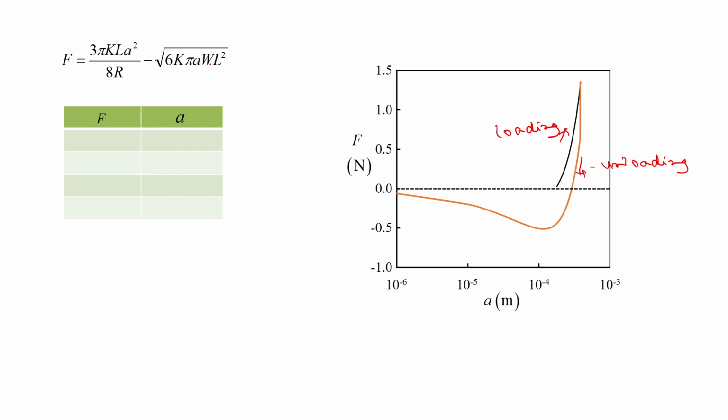So, this is the work of adhesion, right. During the loading part, let us say we start from some finite value of the contact area, at which time the load is estimated to be this. Then the load increases as the load is increased, and along with that the contact area also increases, let us say. Then we